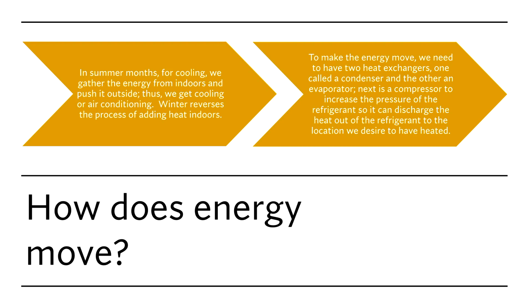Okay, and we can absorb all that energy from the air through the copper pipe in the evaporator coil to the liquid refrigerant and send it over to the compressor, which then squeezes it from low pressure, low temperature to a higher pressure at a higher temperature. And there's some thermodynamic rules that go along with that. But basically, keep it as simple as possible.